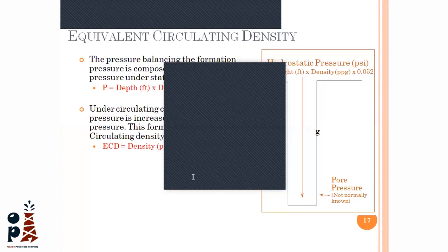So TVD is not measured by anyone. It is just sensors, and we use the drilling line to help calculate this TVD. I'm sorry guys, he asked about the TVD. The measured depth, as I told you, is the length of the connections itself. But the TVD is calculated by the MWD using the inclination and azimuth data, so we get it from the MWD guys. I just confused between the TVD and MWD. The TVD is calculated by the MWD tools. Okay.